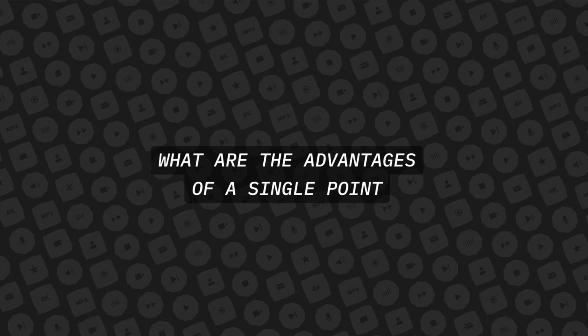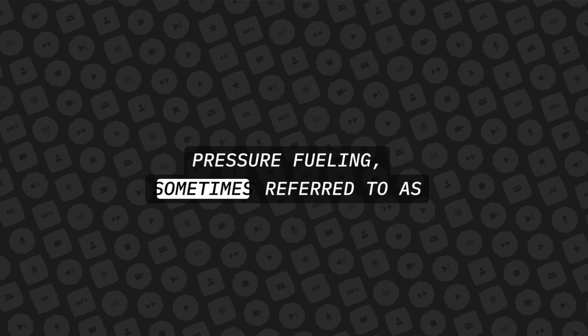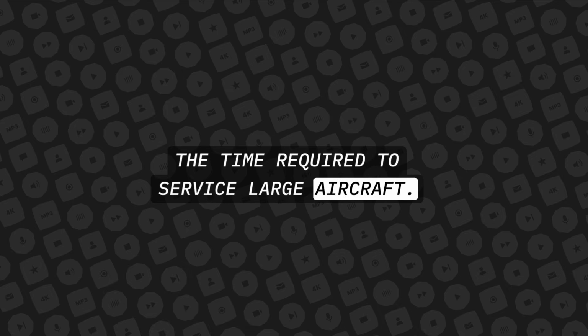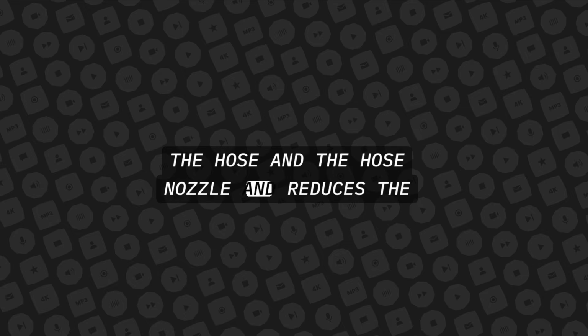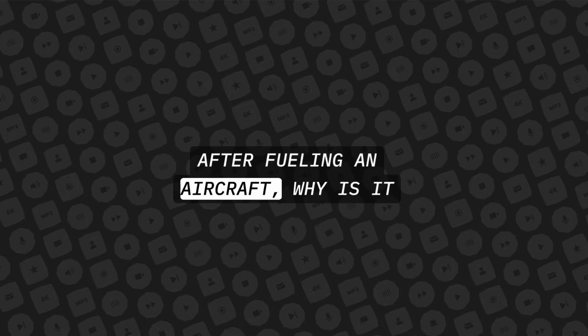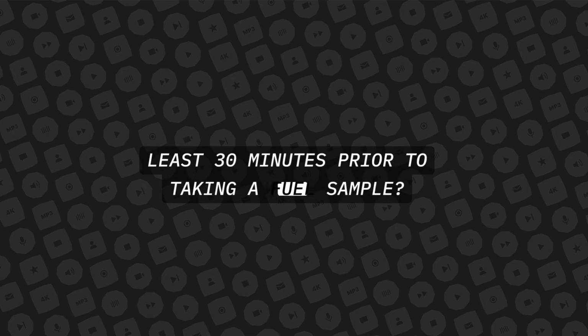What are the advantages of a single point pressure fueling system, and what is it sometimes called? Pressure fueling, sometimes referred to as single point or underwing fueling, greatly reduces the time required to service large aircraft. It also eliminates aircraft skin damage from the hose and the hose nozzle and reduces the chances of fuel contamination. After fueling an aircraft, why is it important for the technician to wait at least 30 minutes prior to taking a fuel sample?